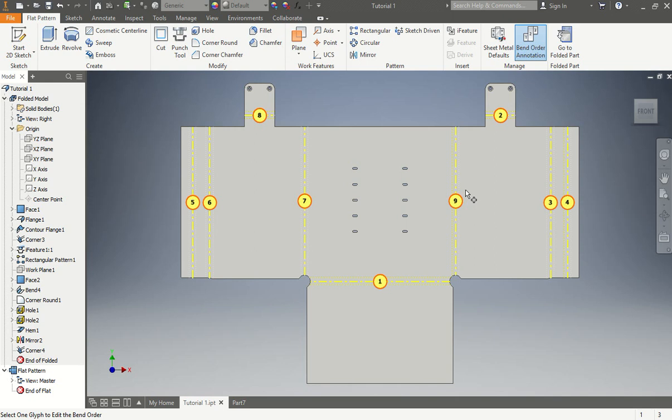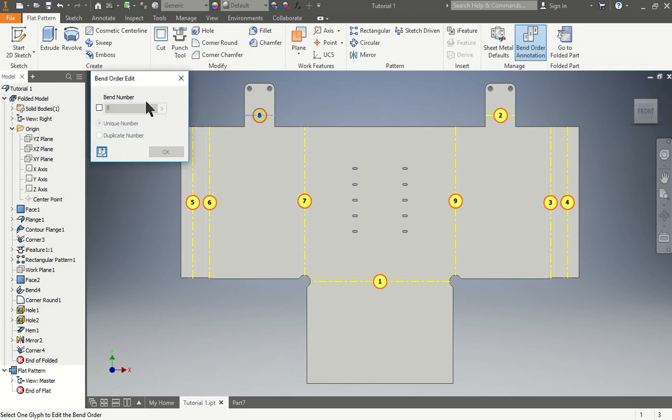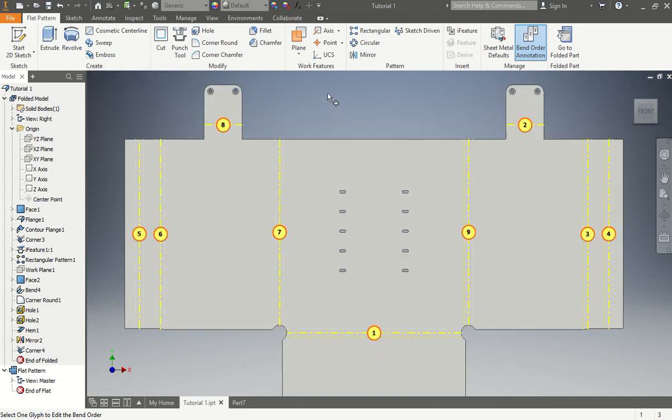You can even select the bend numbers. So if you want to modify it, we could go back here, click on one of them, and you could change it to adjust the number or not. In this case here, we don't really mind which numbers it is, I think, at the moment. No, I think it doesn't affect us right now. So again, if you want to change it, you can just click here, change the number, and press OK. So this is it. That's our flattened sheet piece.